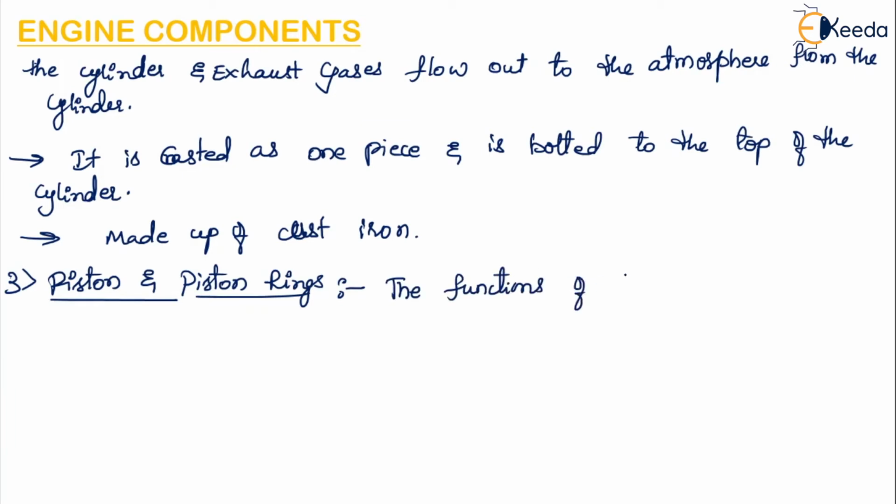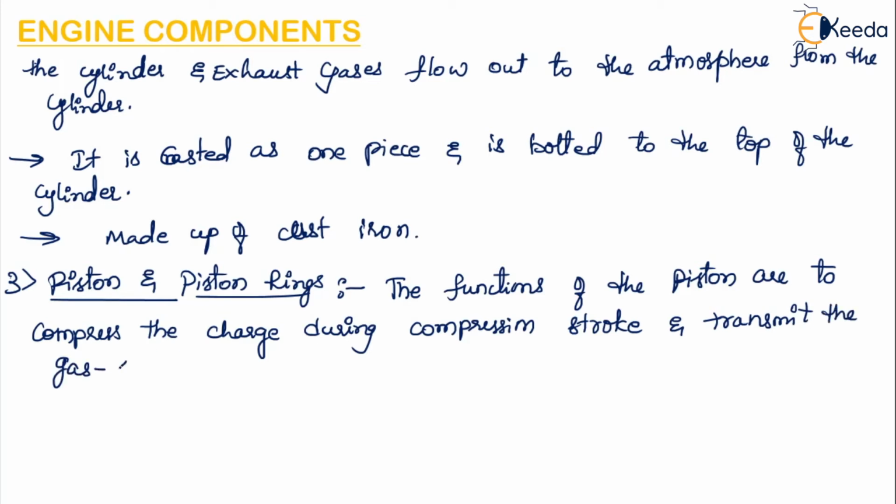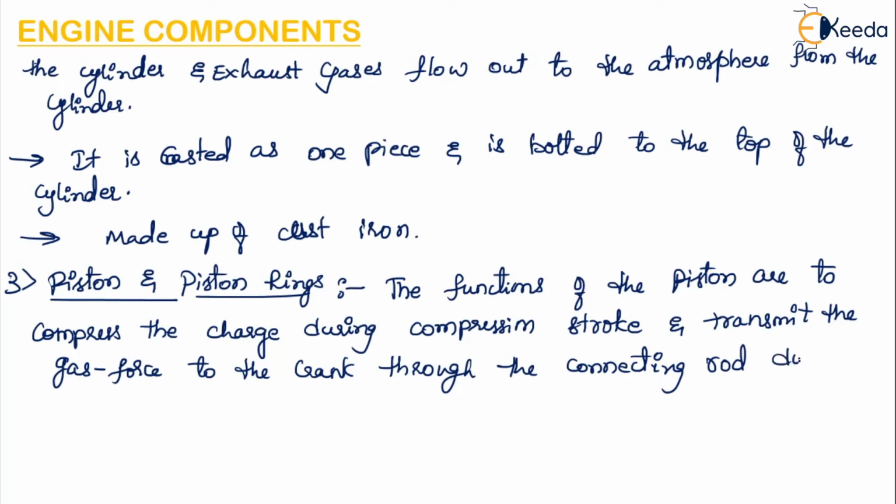Functions of the piston are to compress the charge during compression stroke and transmit the gas force to the crank through the connecting rod during power stroke.